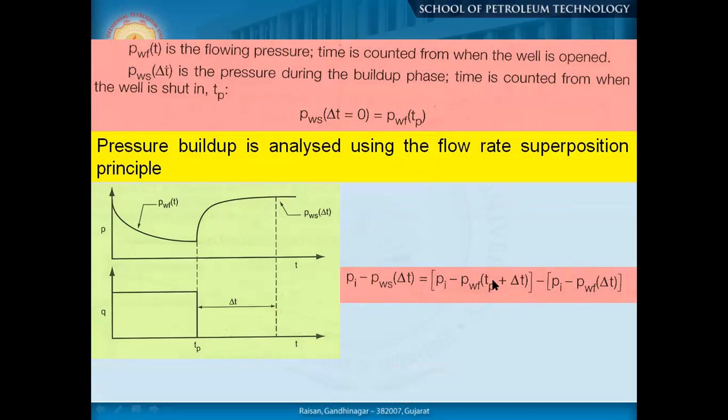So that P, we have to understand if the production is at different times they have produced. So we have to take the cumulative flow rate, the average flow rate, or somehow manage how much production is done and how much time it has flowed. That's why if you divide the total production by your production time, you can get a Q, particularly this line Q and the TP. Okay, so that is actually the normal part which we get from our production data and the production time.